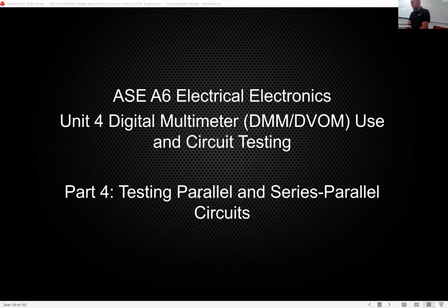Red comes off of here, goes through the switch because it's closed, right? Goes here. And remember, A5 is not a load, it's not a resistance, it's just the amp meter. Come over here, goes here, goes here, goes here, goes here, right? So it splits 4 different ways and hits all 4 of those resistors, at which point it should basically switch over to being ground.